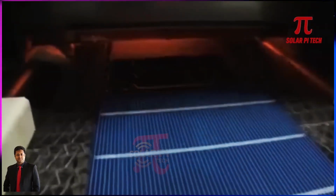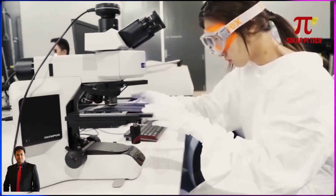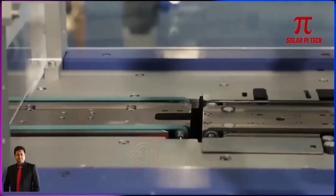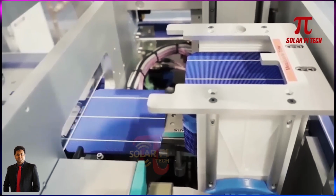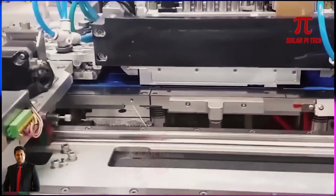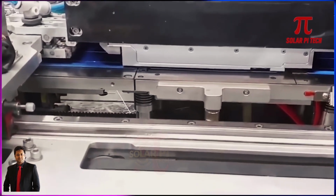The wafer is then treated in a high-temperature furnace, where phosphorus is diffused into the surface to create a negative electrical charge. This, combined with the boron-doped region, forms the essential PN junction necessary for solar cell operation. Solar panel. After this 6-year class in chemistry and physics, which we did in 3 minutes, we go to the fun part, assembly. The solar cells are interconnected to form a solar panel, with various configurations available depending on the desired output and application.